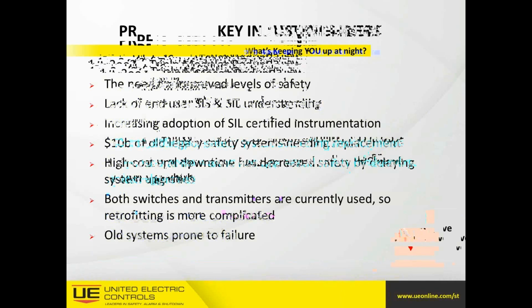Prior to 2010, it was very acceptable to use a communicable device, such as HART. But once the 2010 assessment was put into practice, it then called out that communicable devices are not assessed by, say, EXIDA or TUV. They're not assessed. It cannot be used as a means to detect or report a device's condition. And the reason for that is because the cybersecurity assessment of 2010 does not allow that.